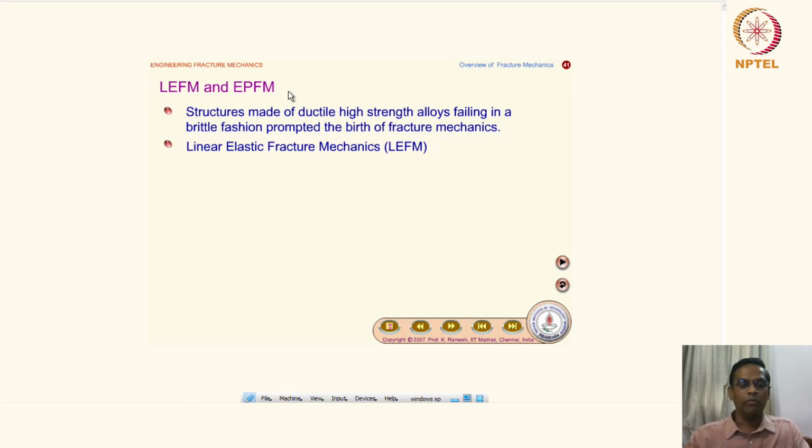LEFM and EPFM. What is LEFM? Linear elastic fracture mechanics and elasto-plastic fracture mechanics. We are going to see them also. Okay, what are they? Structures made of ductile high strength alloys failing in a brittle fashion prompted the birth of fracture mechanics. Okay, this is the bottom line. Why does fracture mechanics become so important? Because people believed that ductile high strength alloys would never fail in a brittle fashion. So then people started looking at them seriously.